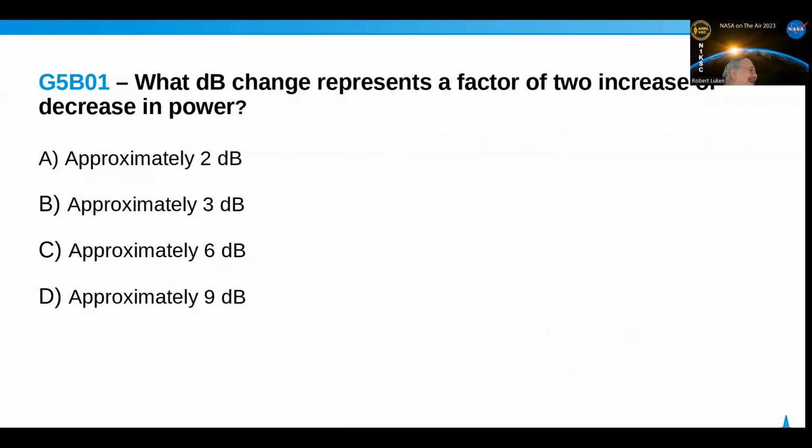And I'm going to throw in a weird one, because we're generally not using directional antennas. You actually have to quadruple your power to double your effective range or distance, because of the square law. Power is radiating out in all directions. So if I'm running 5 watts, by 20 watts I've effectively doubled my range.